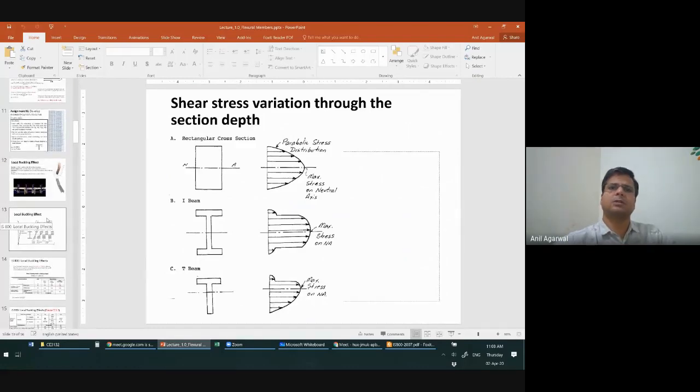So far, we have discussed only the limit state of yielding, right? And within the limit state of yielding, there were three additional factors that we accounted for. The first one was the difference between My and Mp values, right? So the first moment corresponds to the moment of first yield. The second moment corresponds to the plastic moment capacity, right? So these are the first important aspect. The second important aspect was